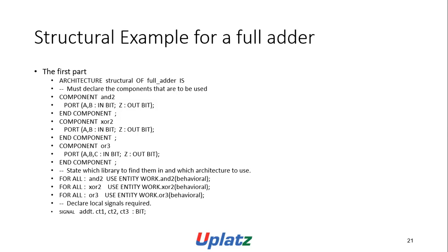For all XOR2 use entity work.XOR2 behavioral. For all OR3 use entity work.OR3 behavioral. Declare the local signals required: signal CT1, CT2, CT3 bit.